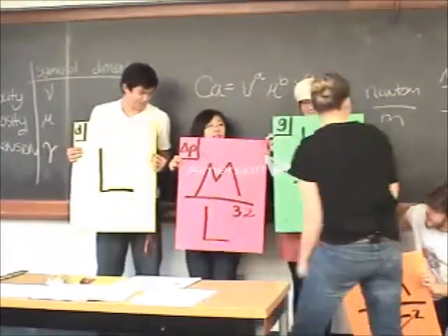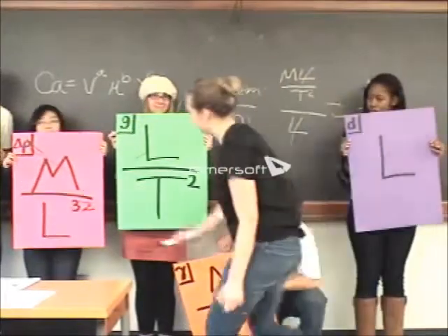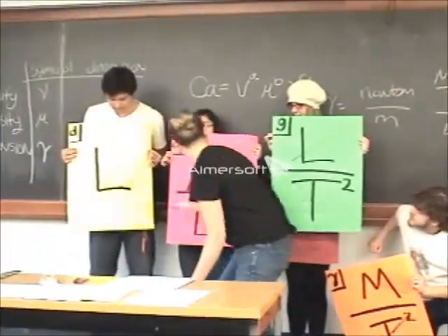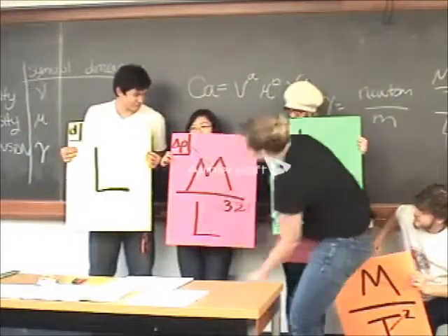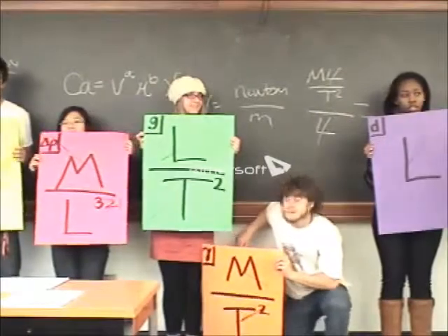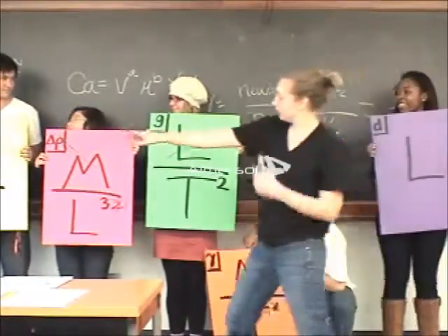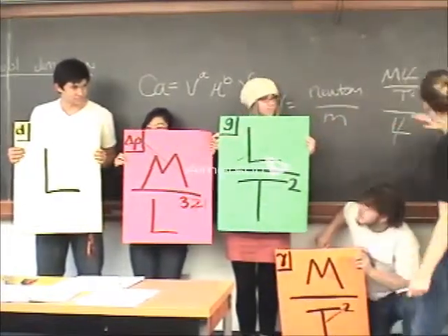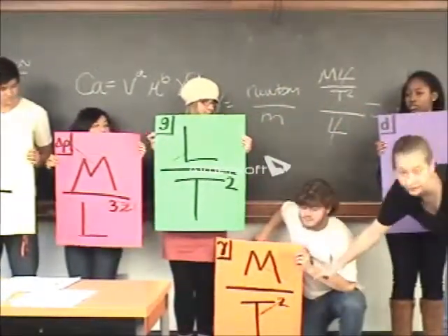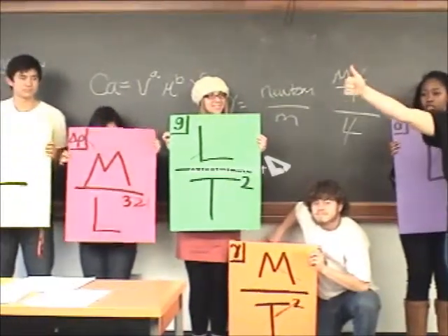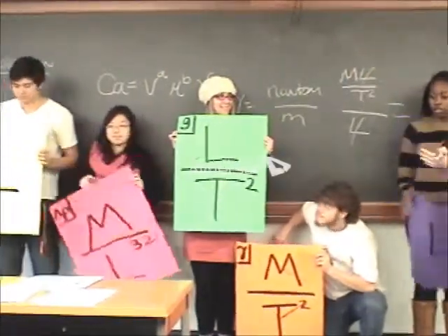Okay, so we can take this one and cancel this one with one of those, so we have one left. We can cancel this one, so we have none of those. So how many units do we have left? None. So we have our dimensionless group. It's D times delta rho times G times D all over surface tension. Yeah? Good. Thank you. Fabulous round of applause.